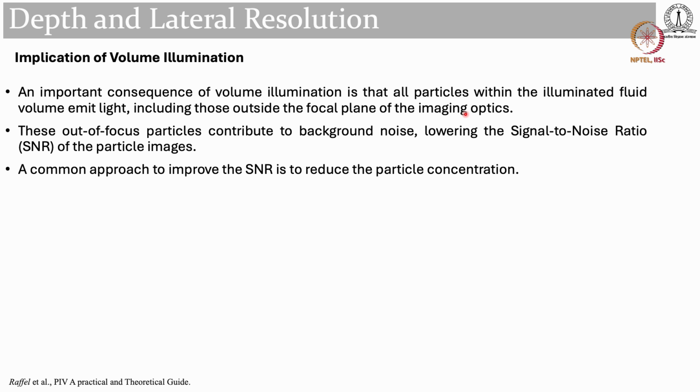And this term called signal to noise ratio is one of the most important parameters while assessing your post processing data. If your signal to noise ratio is very high, then it's better, because that shows that the noise compared to your relevant signals is very low. However, if your background noise starts to become significant, then this SNR becomes very small, and this can actually give inaccurate results.